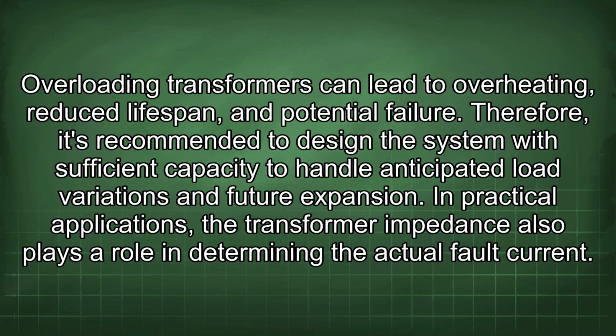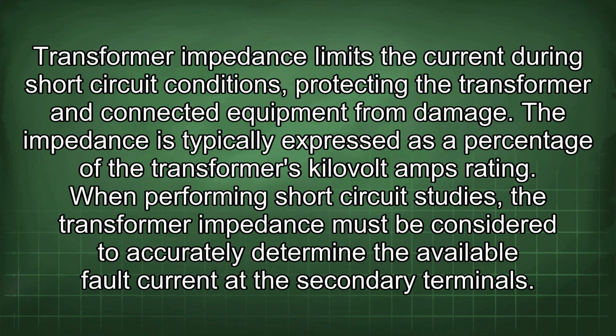In practical applications, the transformer impedance also plays a role in determining the actual fault current. Transformer impedance limits the current during short-circuit conditions, protecting the transformer and connected equipment from damage. The impedance is typically expressed as a percentage of the transformer's kilovolt amps rating. When performing short-circuit studies, the transformer impedance must be considered to accurately determine the available fault current at the secondary terminals.